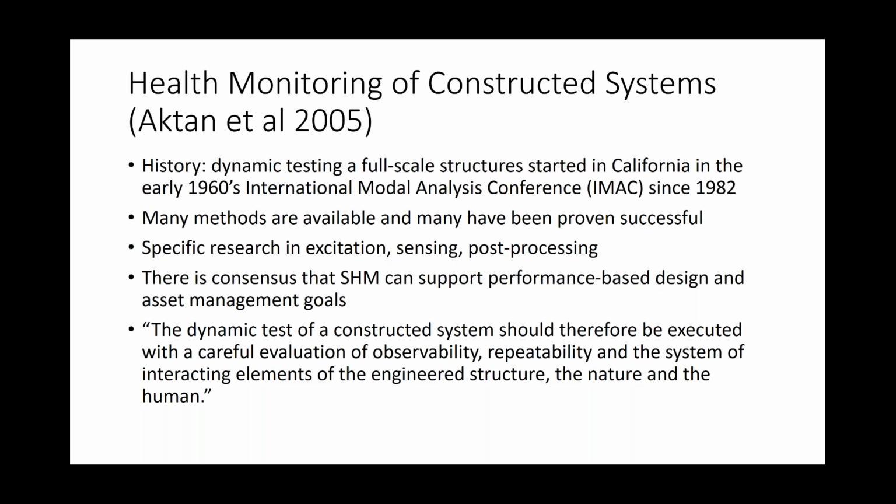There are a lot of methods available. Many have been proven very successful, and it's a very hot area of research with a lot of ongoing work all around the world. Most of the research revolves around how you excite a structure, how you sense the response of the structure, and then how you post-process the data and the algorithms you use in order to identify these important parameters. There's certainly consensus that structural health monitoring can support performance-based design, and that we can use it to consider how we manage our infrastructure assets.